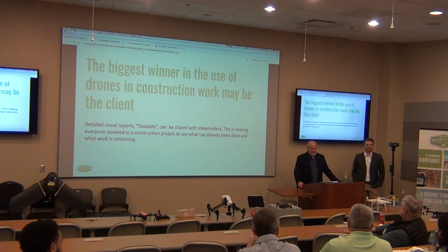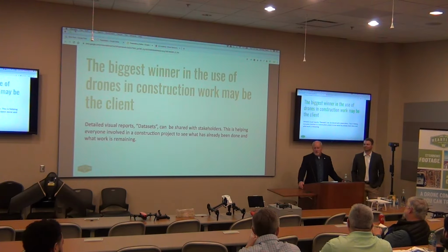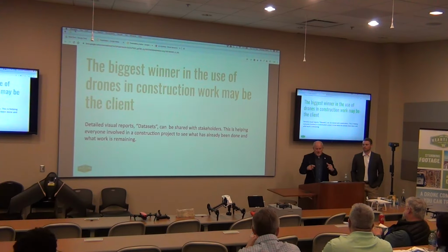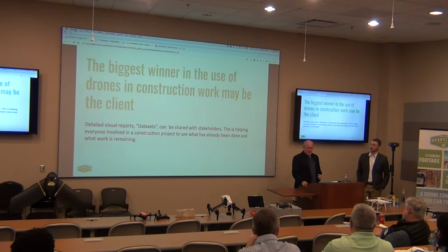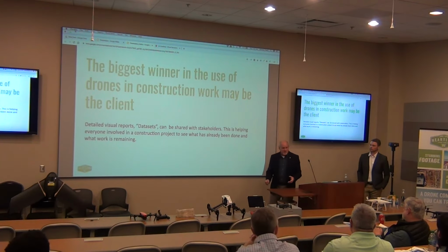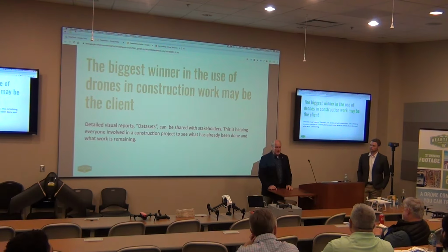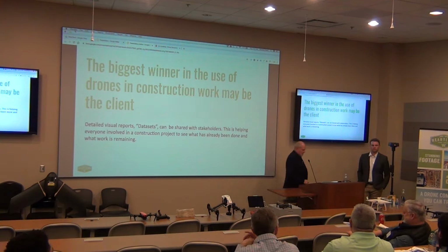Yeah, 2 feet into the neighborhood. So for planning, I would call it the missing piece of the puzzle right now, because you could survey the lot, do an overlay, a topographical overlay, a plan overlay, and you could extract by clicking on your computer screen the exact GPS coordinate that you could send somebody out there with a rover set up and say, this is the corner of this building. There's the money.